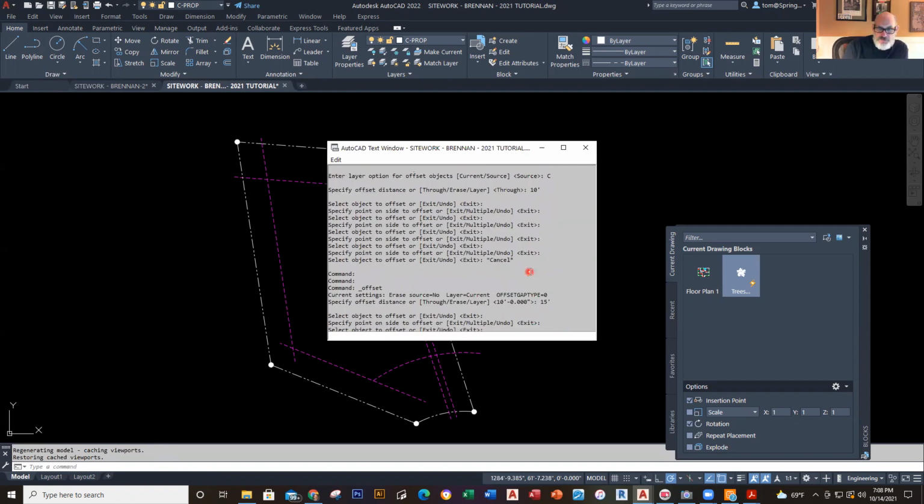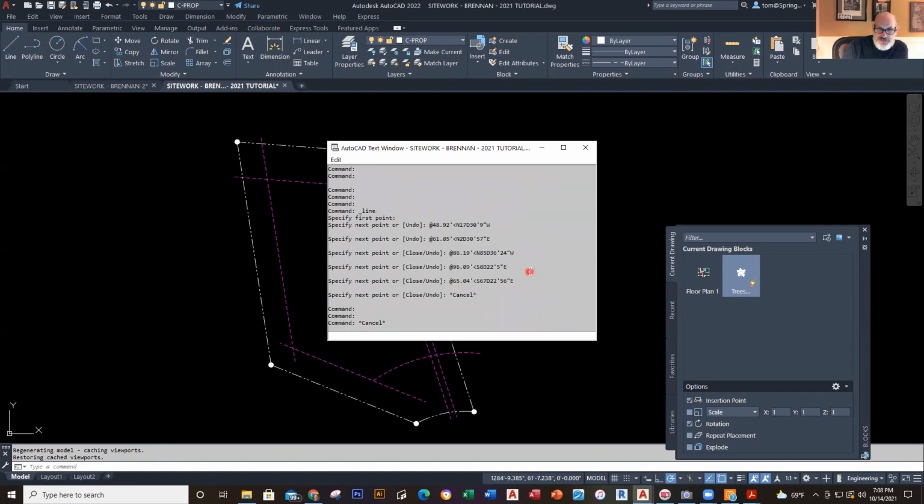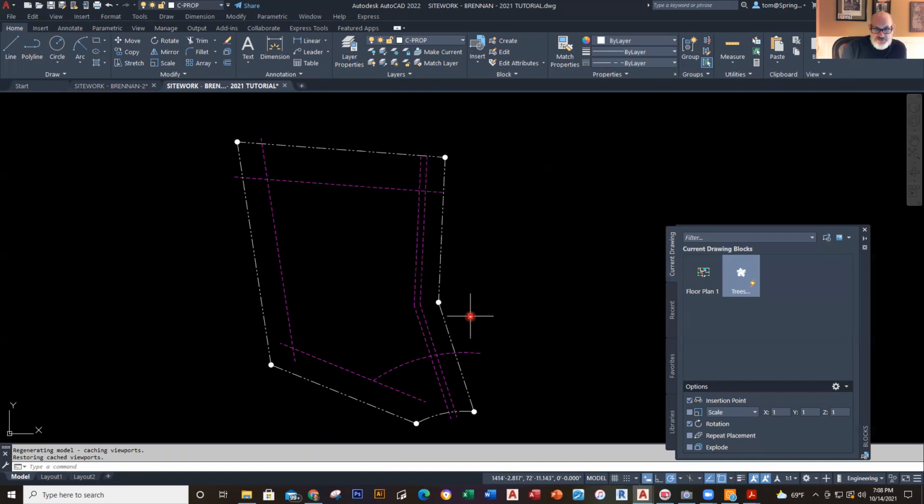Okay, so if I go back to the very first item that I put in here, which is my 48.92 feet right here, you notice that it says this 48.92 feet, and it's got this information here. So if I go ahead and click and grab all this right here, I can grab that whole thing. I just went ahead and selected it. To copy it, I could use Control C, or I can go to Edit and go to Copy. Now, once I got that copied, I'll just go ahead and close that out temporarily.